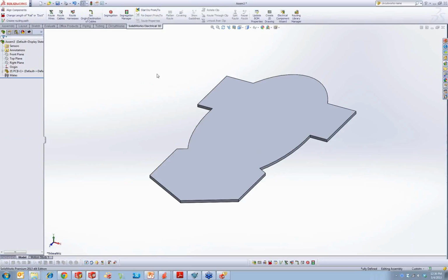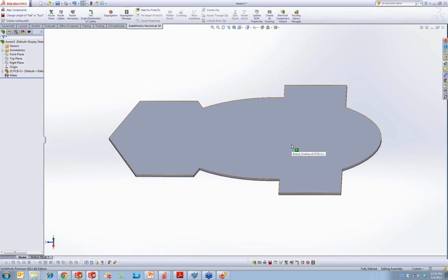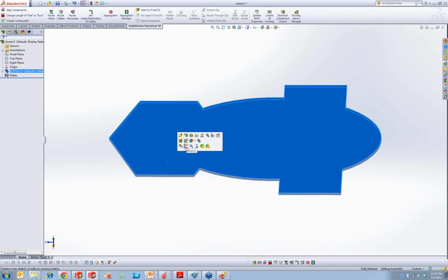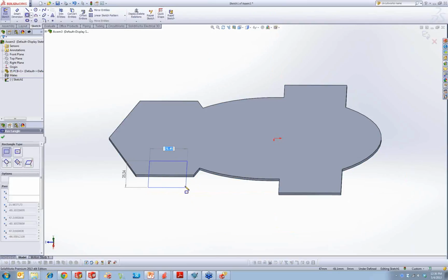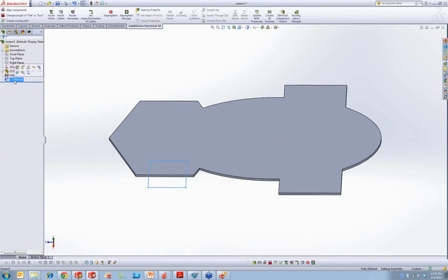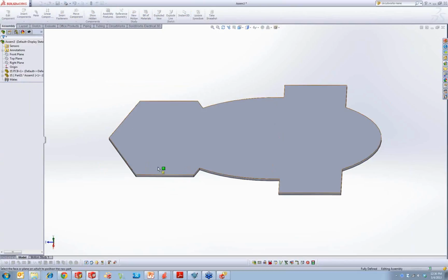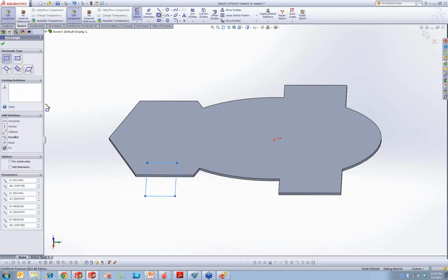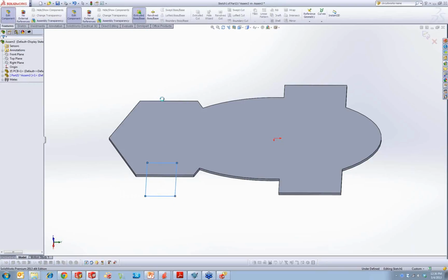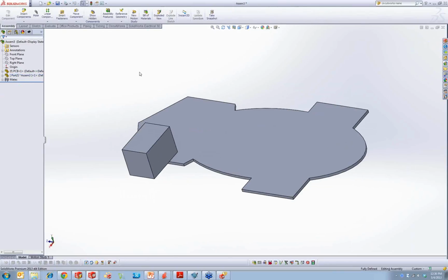All right. Now I want another component on it. I might have some kind of custom connector. So I'm going to insert a brand new component here. I'll drop in a sketch. And I should have created a new part first. Let's do that. Insert a new part. Tell it to be placed on the top of the board. Insert my custom connector. Extrude that as I see fit. There we are. That's our new part.